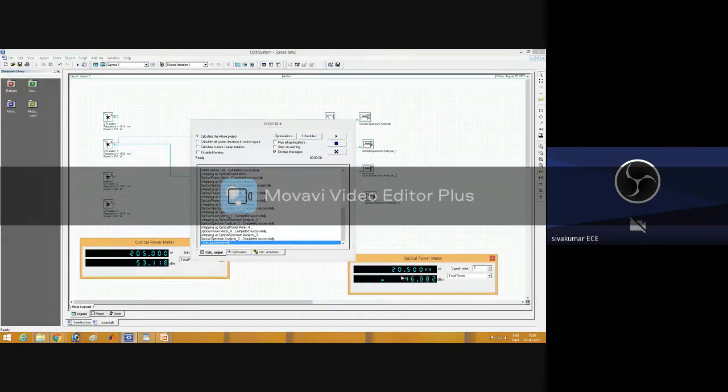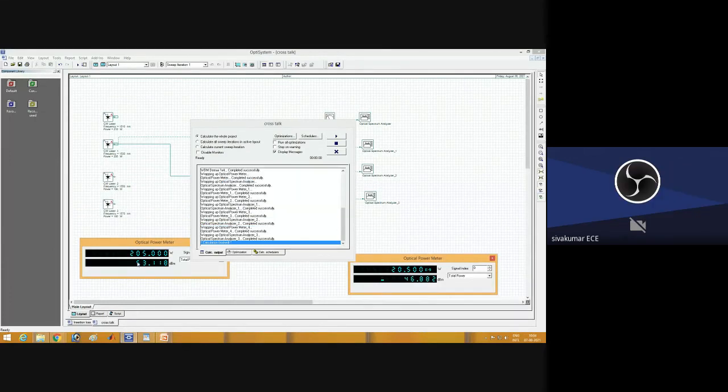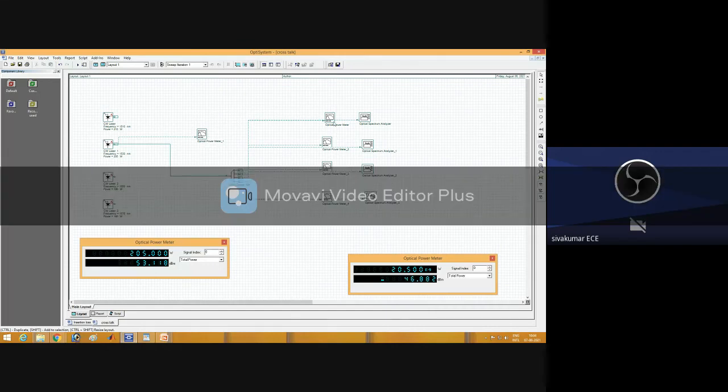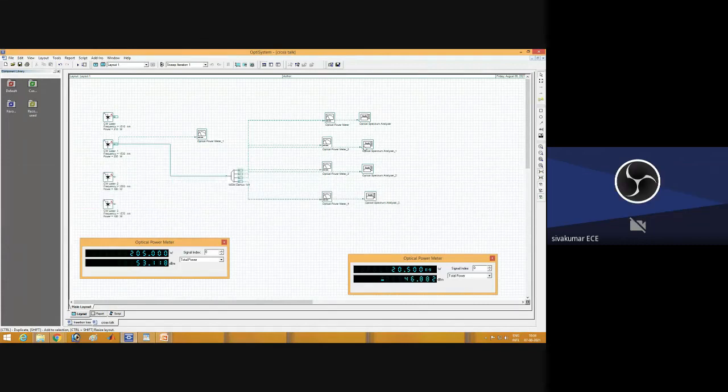It is showing lesser output power: 20.50 nanowatts at an input power of 205. In this manner you calculate all the powers and note down the values for 1510. The input power is P1, and the output powers are P2, P3, P4. In this manner, you calculate crosstalk using the formula. Okay, now I think you are getting clear.